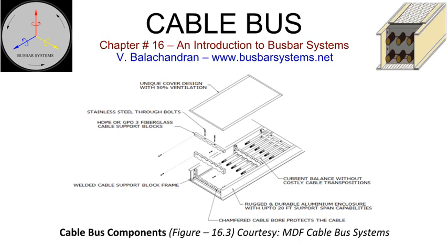This reduces the types of different sizes of slots. The space between the two slots is equal to or marginally more than the diameter of the slot. In most configurations, the top and bottom support blocks are identical with slots only on one side. For the intermediate support blocks, the slots are on both sides. The support block assemblies are slid into a channel and held in position, with respect to each other, with stainless steel tie rods. This feature provides flexibility for axial movement and alignment of cables.